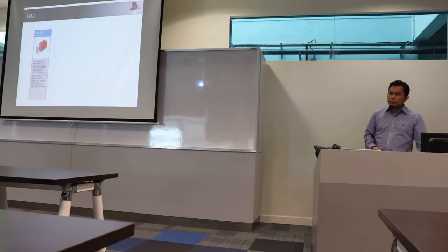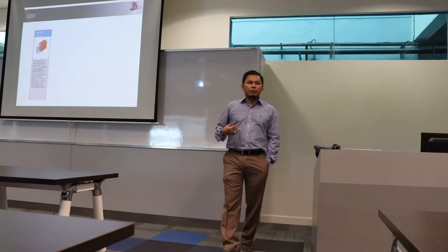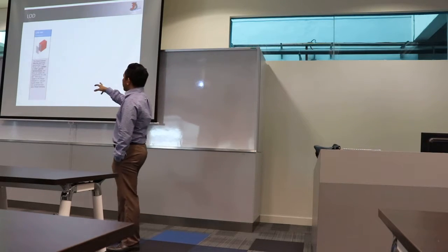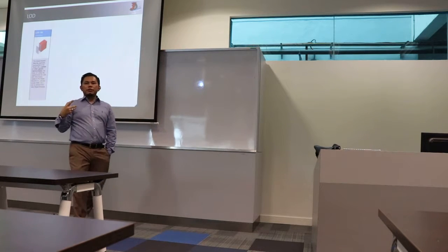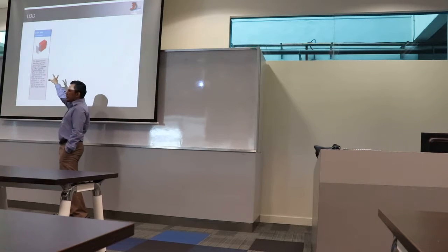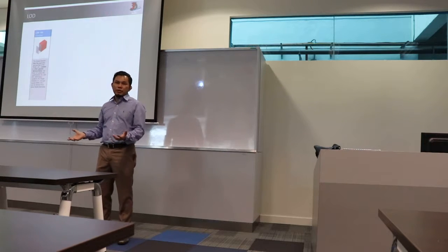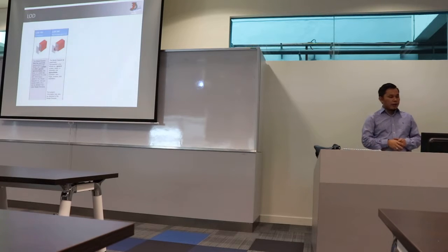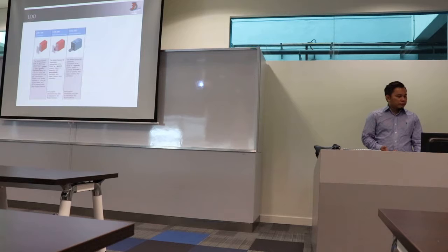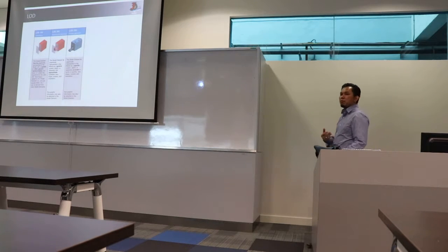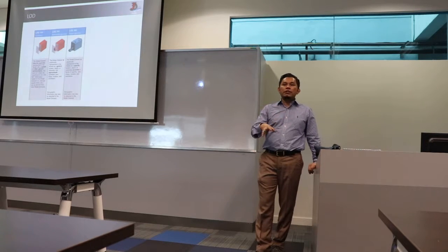Now let's talk about LOD. So what is LOD? LOD is basically with regards to the information that you get from the data that you have. So LOD 100, if you are referring to a mechanical system, let's say this is a mechanical item, you only need to specify the system item, symbolically represented. So at LOD 100, that means very basic information. Then you get to LOD 200, where you start to have a lot more information, and you might also include some non-graphical data. LOD 300, the geometric information becomes a lot clearer, and this is to show mostly design intent, the full design intent of the designer, what they wanted to do.